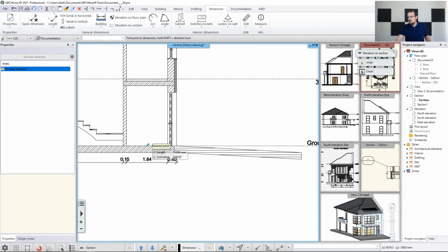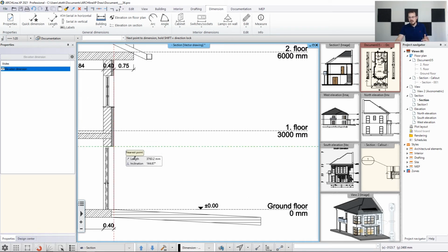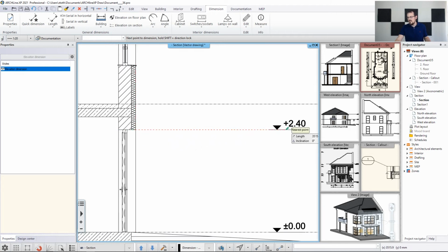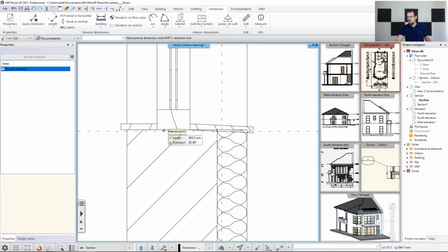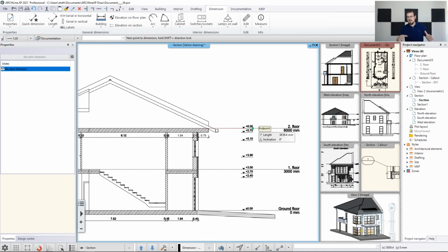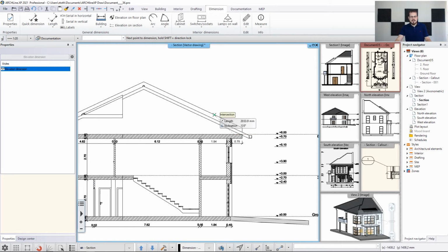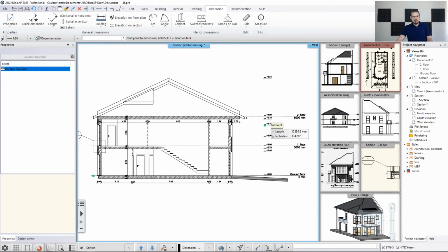And that will be used to dimension the things as we did before on the elevation itself. So what we need to have is the 0 point, and then we use the height of the door, the bottom point of the slab, maybe the top point as well. Maybe you want to get the sill height for this window. For this we have to zoom in to find the right node, and then we go to the height of the window, and where the attic slab starts and where it finishes. Mind you, everything is created as I'm clicking. I'm not zooming out, so that way I can see better what I'm actually working on. And also I think what I need is this topmost point,